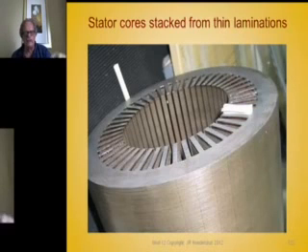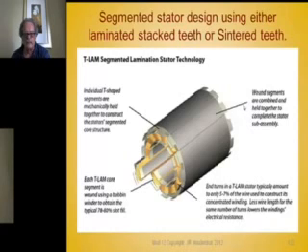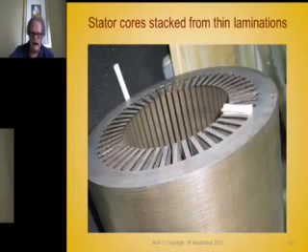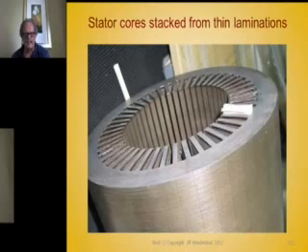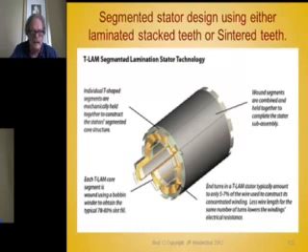And so I should have put a finger plate, a heavy piece of steel that goes on the OD here, and has things that look like the lamination, but they're not. They'll be narrower, and they'll be pre-bent downwards. From this point they'll be bent down. So when you clamp it on the OD, those act like finger springs that compress all these together. I'm going to show you a picture of it later. I should have had those on a machine this big.